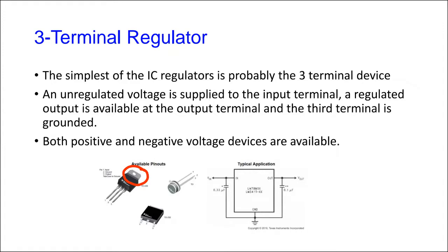They make it in a way that you can mount it. This one here is what is called a surface mounted device, SMD. Right, so this thing here would be very small, probably maybe a couple of millimeters square. Again, it has a heatsink on it, right on the back, and the back of this entire thing is metal, but it's mounted flat on the circuit board. And what they do is on the other side of where it's mounted, you have a big wide area of copper to dissipate the heat. So it's the same process. Okay, let me get back down to here.